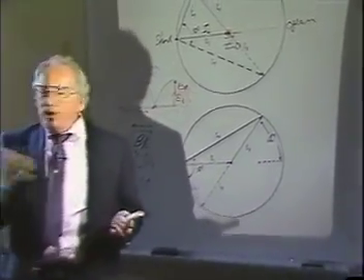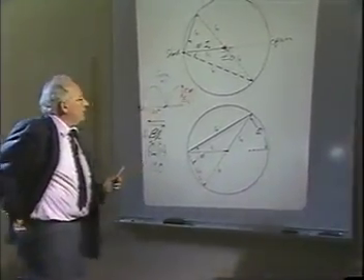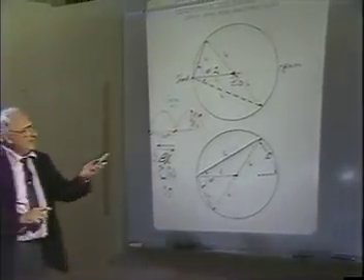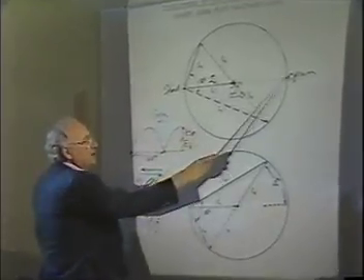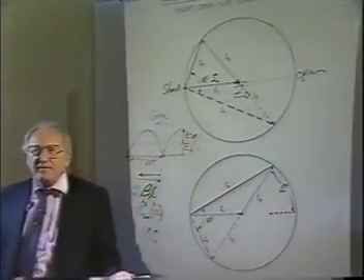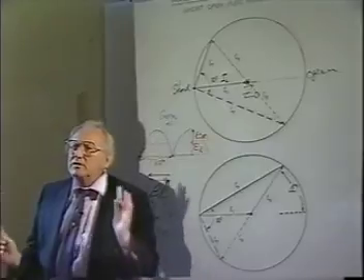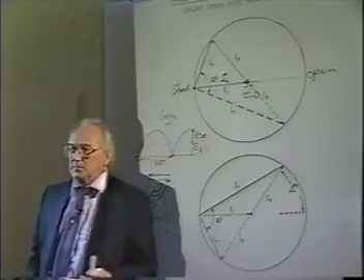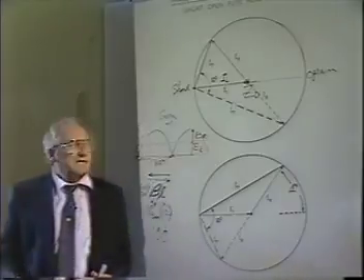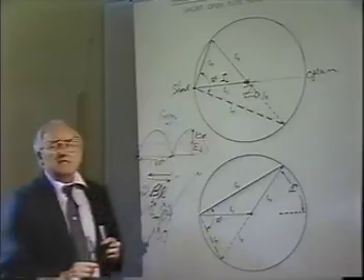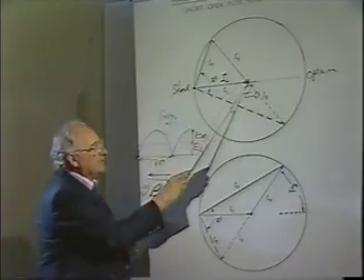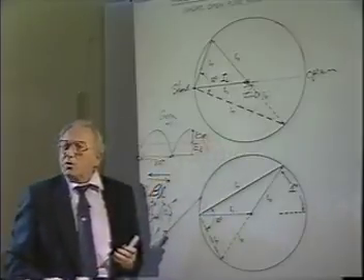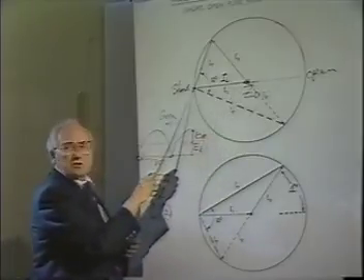We know that when it reflects from the transmission line, you can have other problems. Those problems being that the signal that reflects back will be either in phase over here or out of phase or any phase in between. But we haven't discussed that in-between situation yet. Let's stick with the pure resistance part. Remember we said that if you have an impedance less than Z0, here's Z0. If it's less than Z0, is it going to be going toward an open or going toward the short? Toward the short, because it's going to be less than Z0 in this direction, because here's the short.